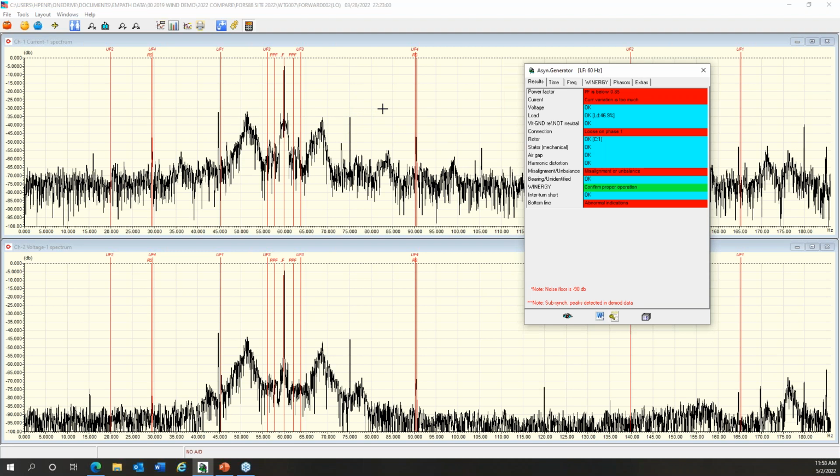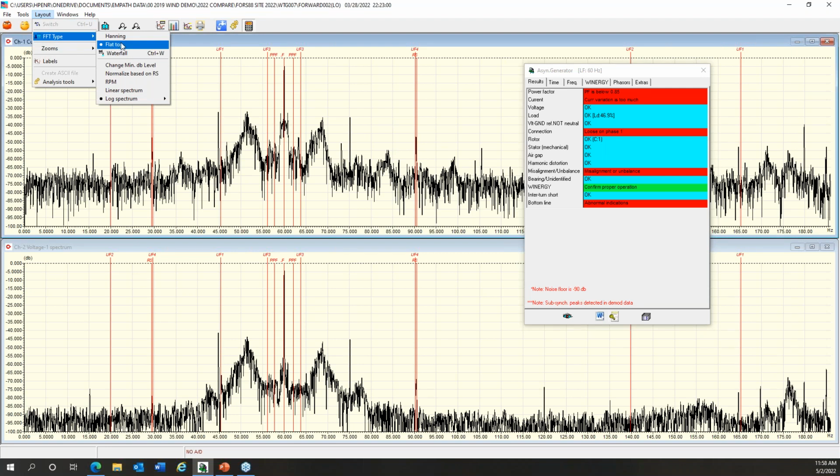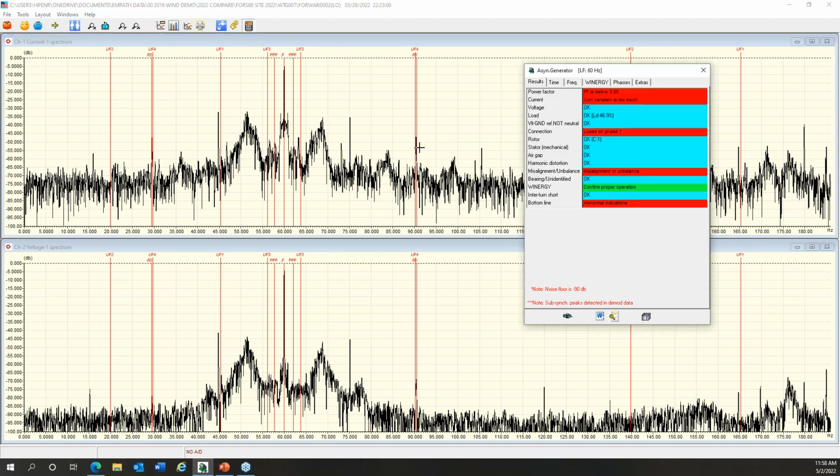And there's another little dirty secret in the industry. Some people with limited experience, to put it mildly, that manufacture some equipment said, hey, if the peak's higher on one side versus the other side, then it's this signature. If it isn't, then it isn't, and they're wrong. The reason has to do with which type of windowing they do. I always use flat top. There's a little more noise, but I usually have balanced results. So in any case, and for those that are into vibration, then yeah, it's all the same.